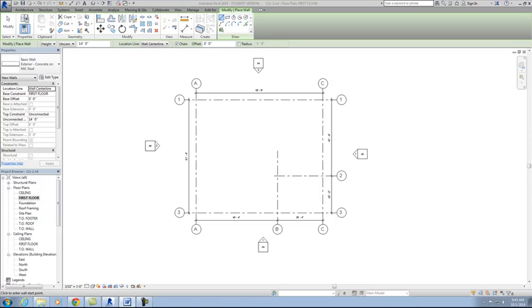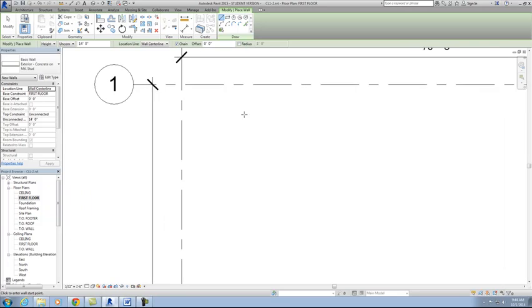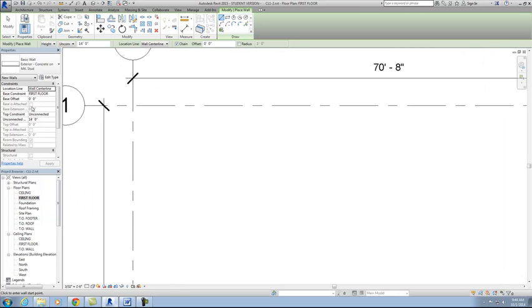So now what we want to do is add the exterior walls to the drawing. We're going to go in a clockwise direction. So I'll start here at the top left corner of my building. And then I also want to check for my constraints. So while we're on the subject here, let's go ahead and set the top constraint to top of wall. So that'll give us the correct wall height at 18 feet. So this way, if I change the top level or top of wall level, it will change the walls automatically. And then our base constraint for right now is set to first floor.